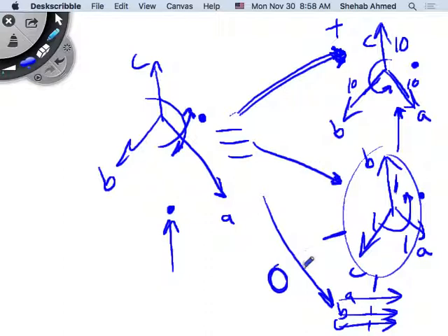So this is like DC braking. DC is one value of voltage in space, right? Is it rotating? No, it's not rotating. It's a voltage where all three voltages are in phase. So if I have three voltages that are in phase with each other, I apply them to a three-phase system. They're not a balanced three-phase 120 degrees apart anymore. So if they're all in phase, what happens? The currents that they will generate will also be in phase.